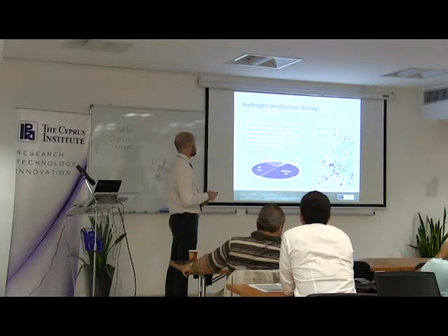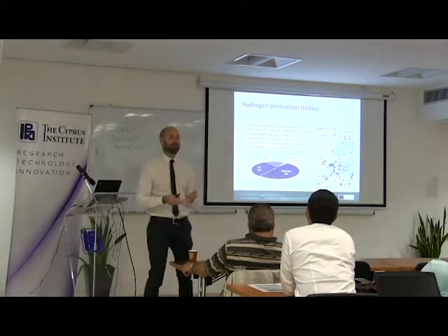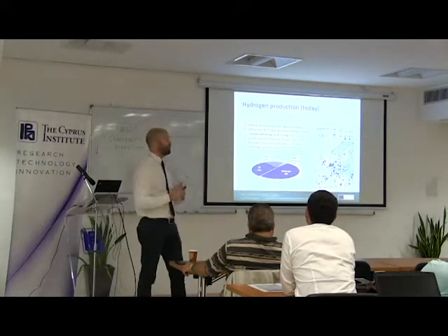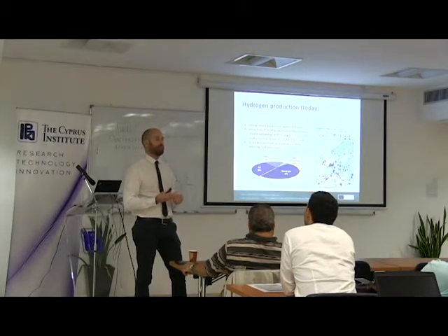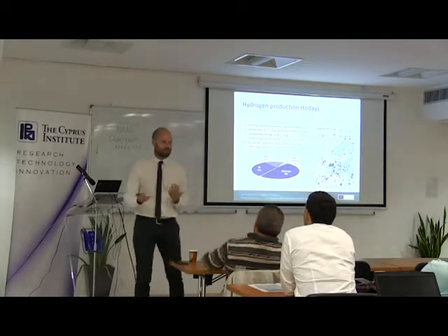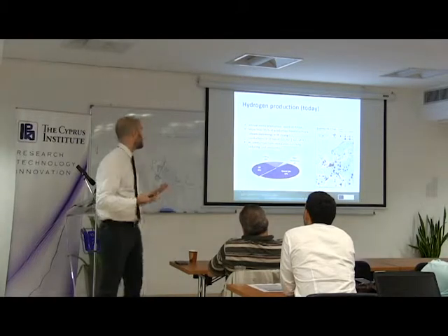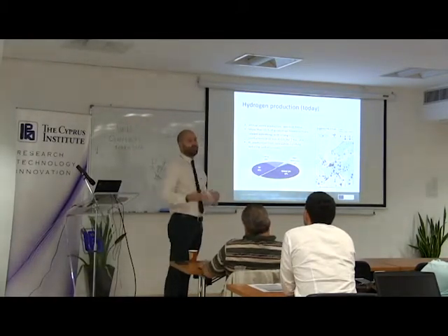And steam reforming entails a big production of CO2, because steam reforming processes are strongly endothermic, which means that we have to provide heat to these processes, and it's really high temperature heat. We're talking about 700 to 900 degrees Celsius to have a significant yield of hydrogen. And how do we provide this heat?